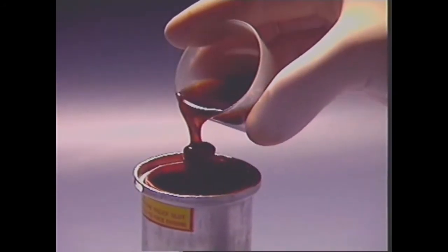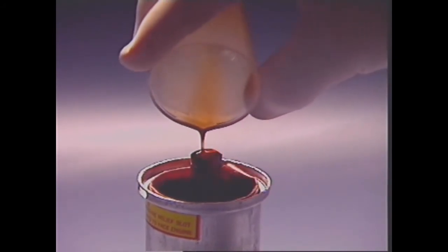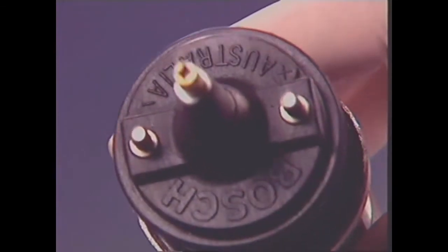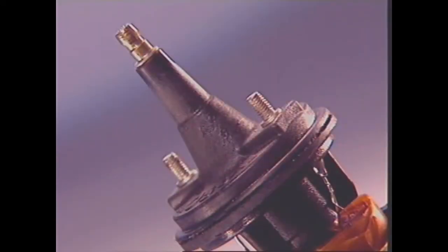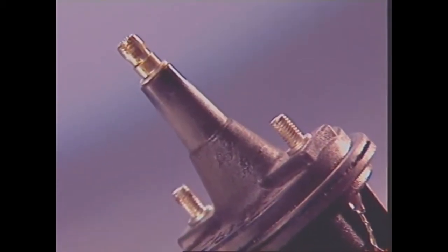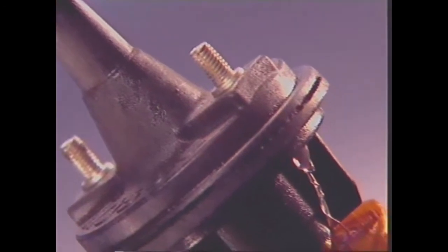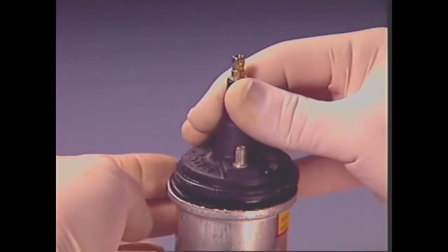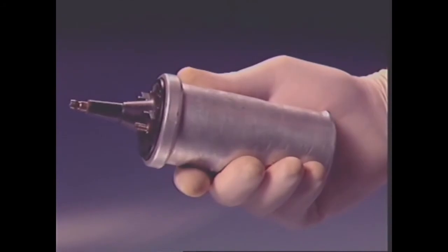The container is then filled with a special transformer oil, which provides good electrical insulation and also permits rapid heat dissipation. The cap has two terminals, positive and negative, for external connection to the primary circuit. The ends of the primary winding are connected internally to each. Provision is also made externally for a heavy insulated center terminal to connect the high-tension coil lead to the distributor cap. One end of the secondary winding is connected to this center terminal, and the other end is connected to one end of the primary winding. A rubber seal and a molded insulated cap seal the assembly in the container, and the container edges are swaged over to bind the coil into a compact, vibration-free unit.